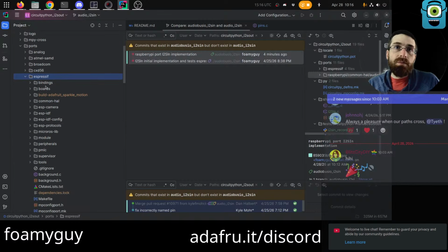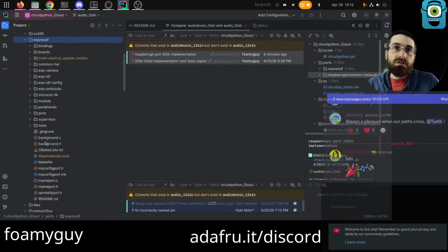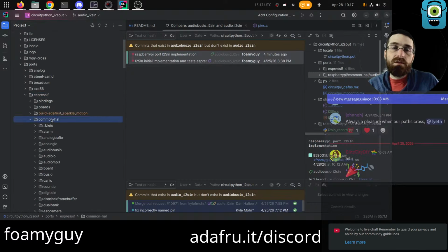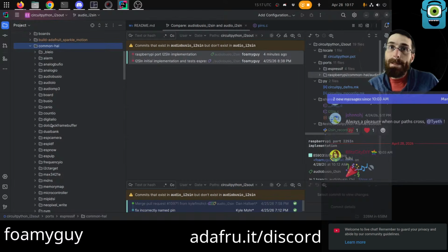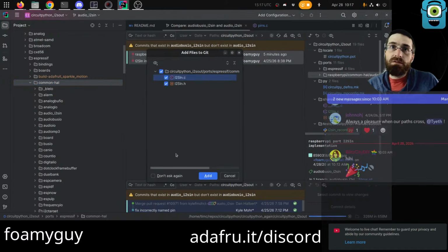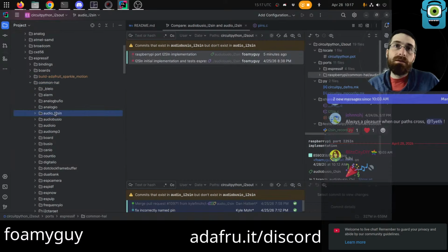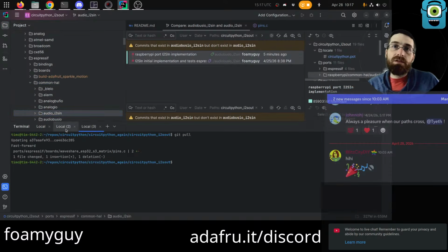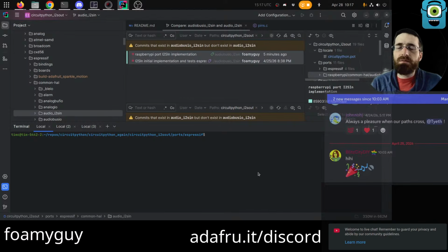I think I'm going to end up upgrading to a different, it's an old computer that I have that's got a bigger hard drive and runs a bit faster than a Pi. Be able to just paste this in here. Okay. Theoretically, that should be all we need to test the Espressif build. So we need to do what? We need to export the thing, right? IDF thing, ESP, IDF, export.